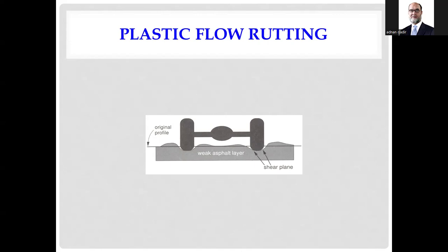Up to what depth it would depend on where actually your rutting is, up to what point. There is no alternative. There is no resurfacing. People think just having say a 2 inch layer will provide you the structure. That will again fail. So the wastage of time and money will be of no use. As a thumb rule, remember it: it must have an actual extra asphalt base layer. It should be strengthened with an asphaltic base layer and then followed by an asphalt wearing layer.